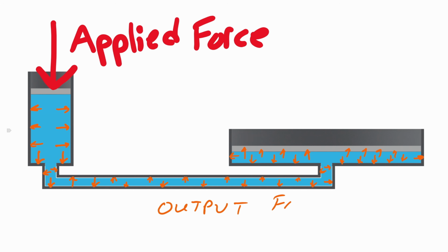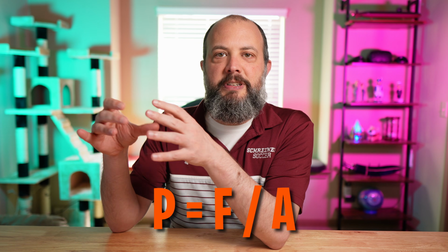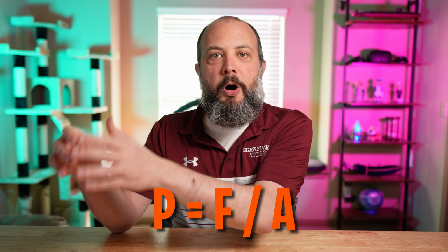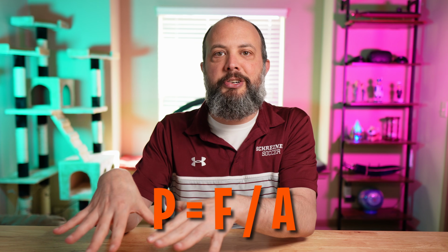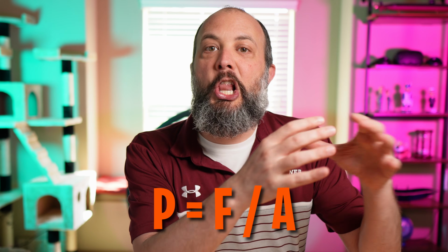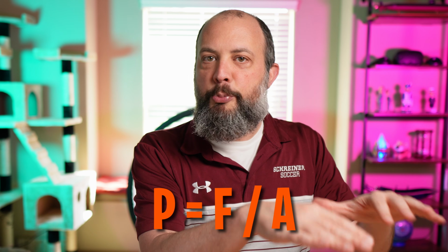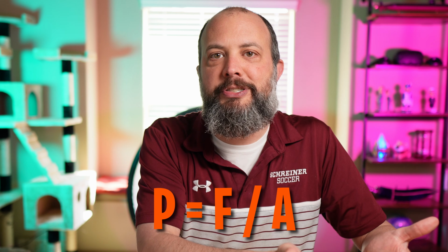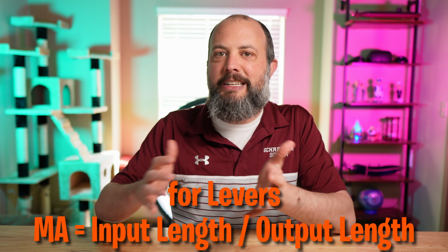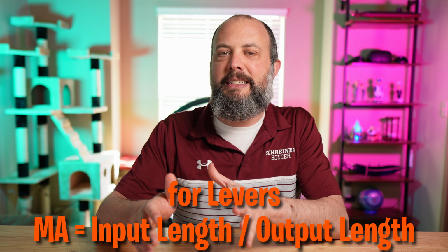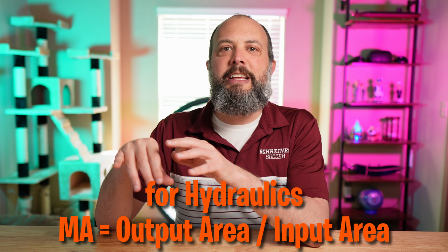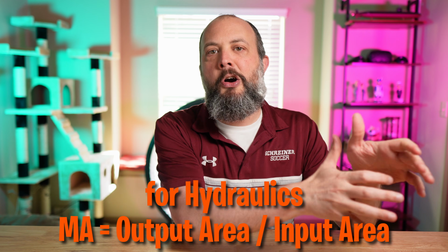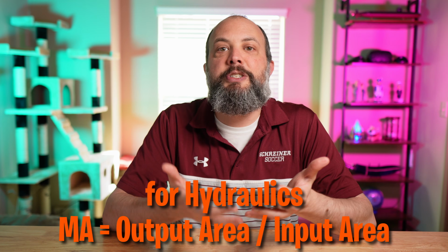The same pressure everywhere. And a mechanical advantage comes from the surface area. Since pressure is force divided by area, a very small area on one side will create a large pressure. So then on the other side, if you have a very large surface area, that same pressure will act over the entire large surface area and generate a very large force. In some ways, this is the same but exactly opposite the way leverage was used back in statics. In statics, a longer leverage arm was more mechanical advantage. So this way, you see if we rearrange the terms, a small input area and a large output area is how you generate a large mechanical advantage.